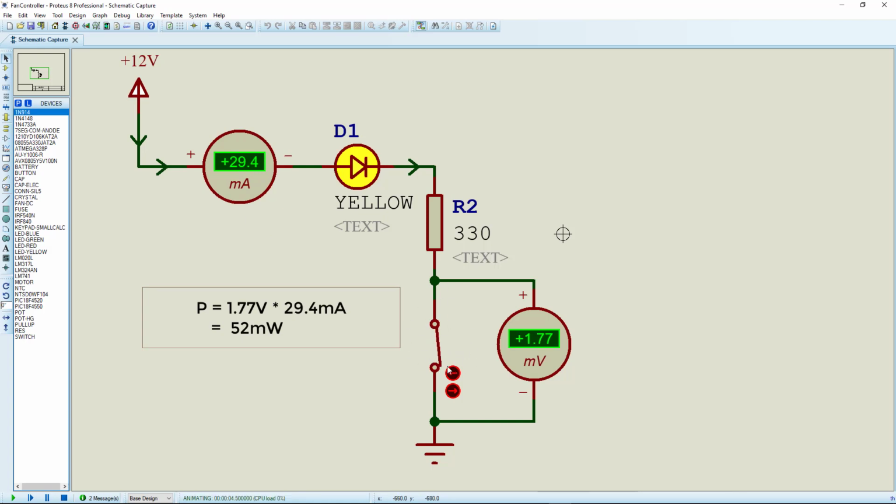Now this is still small, but if you are dealing with microamps of current and low power circuitry, this is very significant. And this is why it is very important to know the on resistance of your switch.